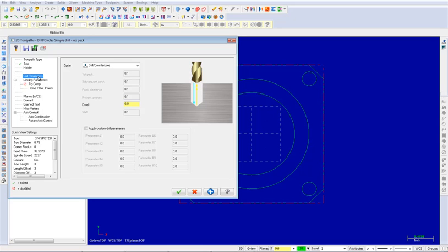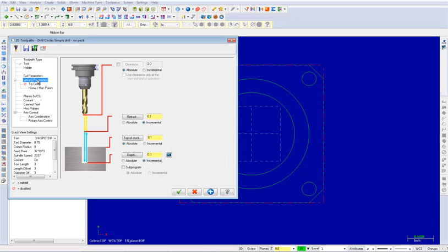From here, select the linking parameters. Ensure that clearance is enabled and set the top of stock and the depth to absolute values of -0.5. To input the depth, select the calculator icon as shown.